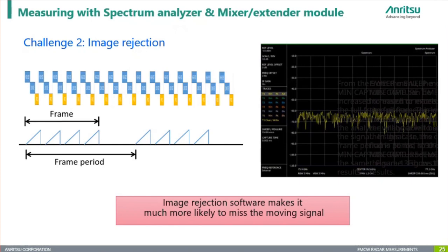Sample mismatch between the processing stages can lead to inaccurate or flat traces. As a result, many FMCW signals fail to appear correctly, often displaying as a flat line, providing no useful diagnostic information. This limitation makes it difficult to characterize radar signals effectively, especially in applications requiring precise pulse analysis.